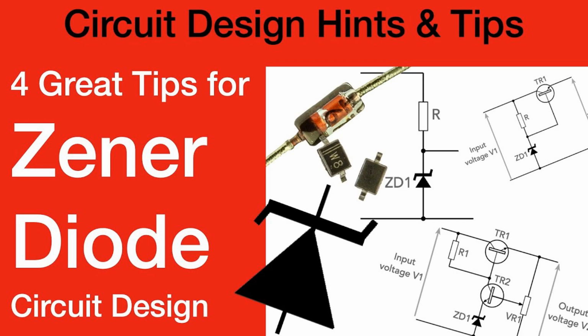2. Overvoltage protection circuit. Components: Zener diode, VZ equals 12 V. Load device, e.g., microcontroller. Circuit description: The Zener diode is connected in parallel with the load device. If the input voltage exceeds 12 V, the Zener diode conducts and clamps the voltage, protecting the load device.